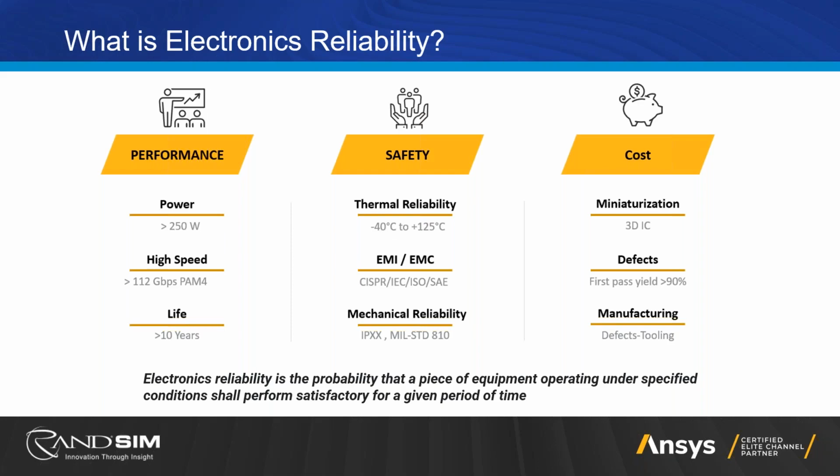And then EMI and EMC. This is really common when you're dealing with getting through that carrier's regulatory certification process. Is my device making too much noise to pass? Is it going to interfere with other devices, or is it going to have implications that are negative on the performance? If you have a medical device and it's susceptible to EMI, then it may operate incorrectly and cause issues. And then the mechanical reliability. There are standards, whether it's military or IP, that are necessary to be upheld for those safety points.